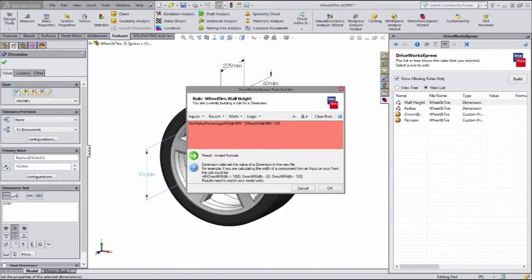And to get the correct decimal point, we're going to want to divide that by 100. And then, to get the conversion, we're going to divide that again by 25.4, giving us a tire wall height for this example of a little over 3 inches.